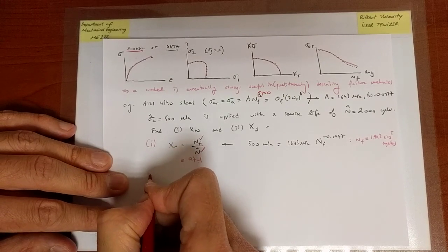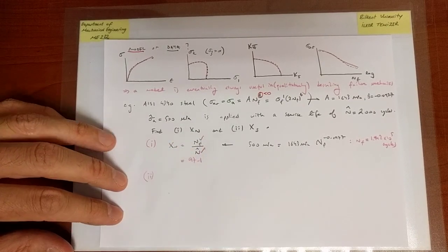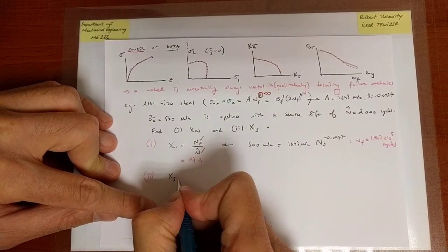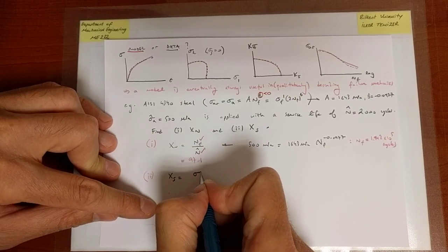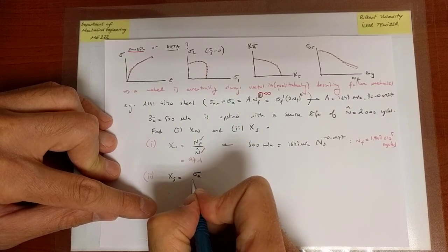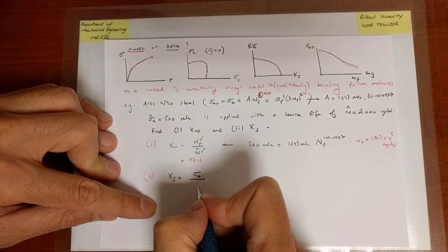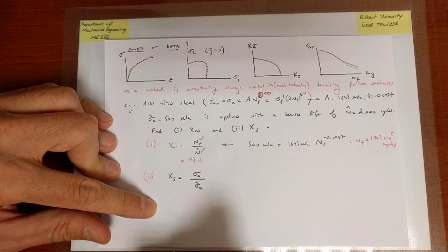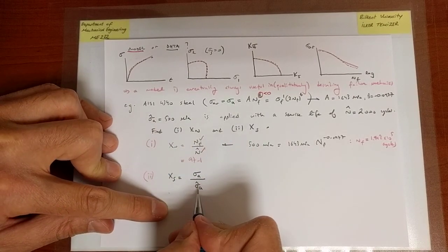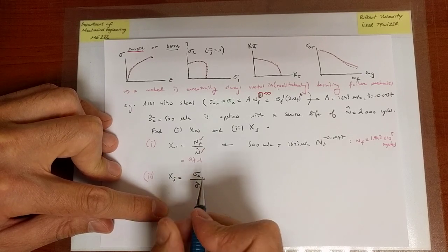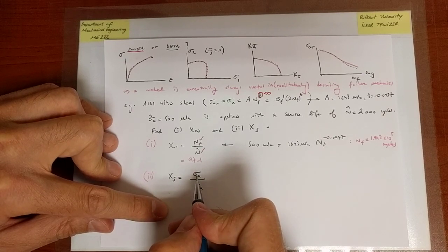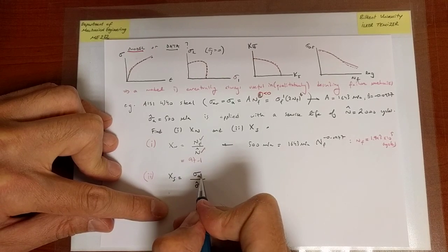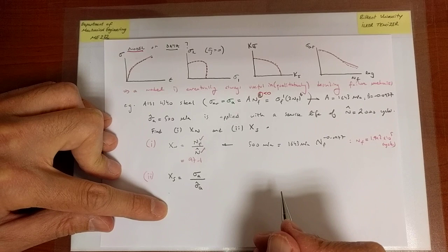So now we proceed into the safety factor on stress. Now, the way we calculate the safety factor on stress, remember, is there is a certain stress that causes failure, and on the other hand, we do not really want to cycle at that value of the stress. We operate at a smaller value. The operation value is 500 MPa. The stress value that would cause failure under our operating condition is the value that will lead to a life of only 2000 cycles.